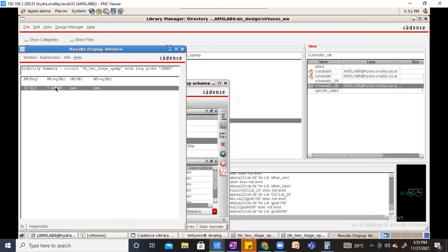Any questions? Hello. Yeah. Sorry, the unity gain buffer is a closed loop system, right? Yeah. So our phase margin has increased from the open loop system to the closed loop system? Could be. Yeah, because you are closing the loop. So the pole locations may vary. It will definitely vary, by the way. And because of that, your unity gain also will vary, and your phase margin will also vary.